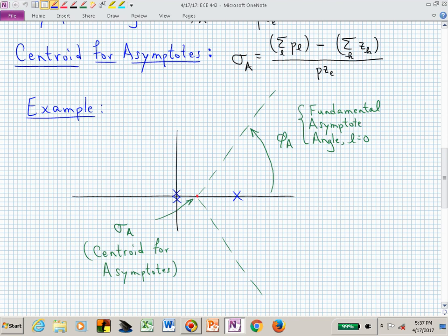And if we subdivided this infinitely long real axis, how many segments would belong to the root locus? How many ways have we cut the bread? Okay, we've cut the bread into 3 pieces, right? Because those 2 poles at the origin are on top of each other. We now have 3 real line segments. How many of those segments belong to the root locus? Now we don't want 3, we want 2, don't we?